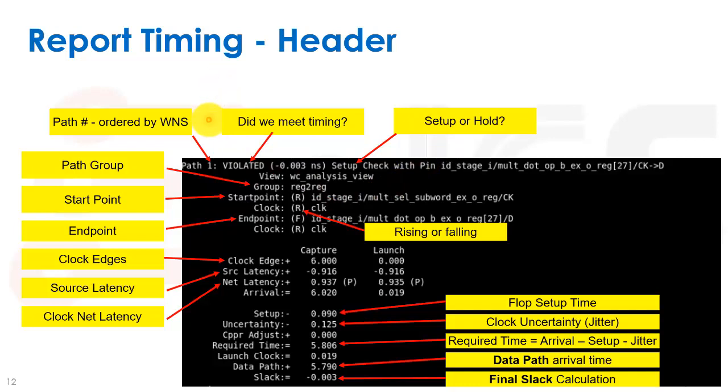They have a lot of information, and we're going to look at them a lot. And of course, the actual format that it spits out is dependent on the tool. In a Cadence tool and a Synopsys tool and a Mentor tool, they're going to be different. And number two, it depends on the version of the tool you use, because sometimes they work the function that makes this and it spits it out differently. Plus, we can also configure these timing reports with all kinds of commands to make them look different. But we really have to know how to read this.